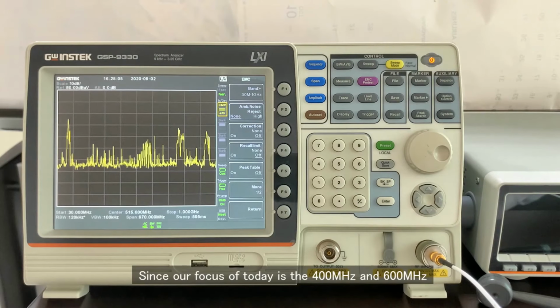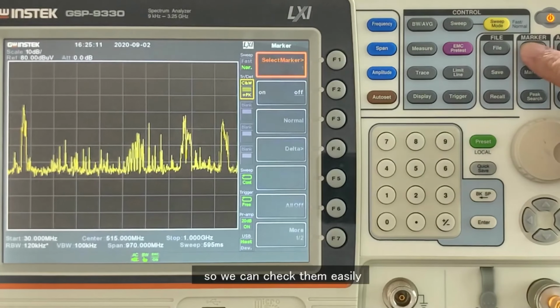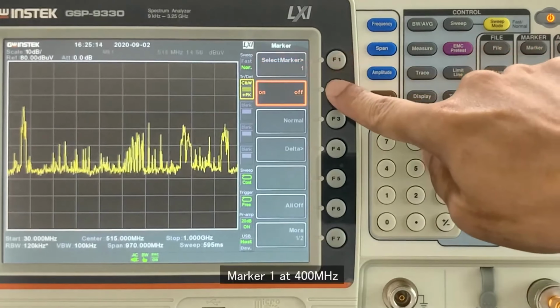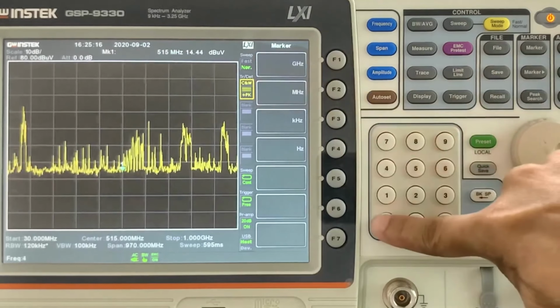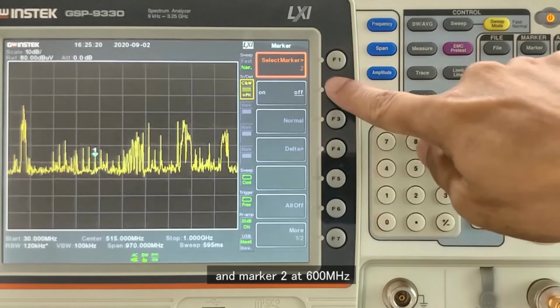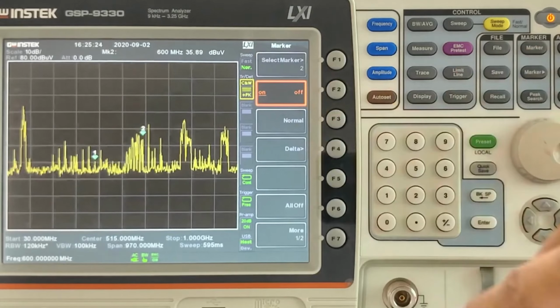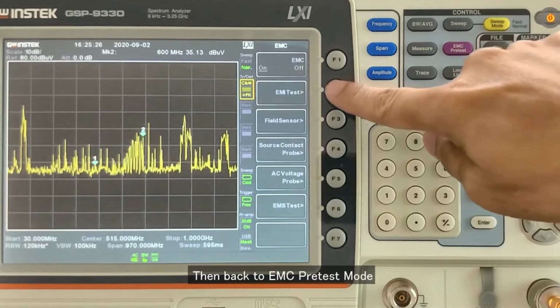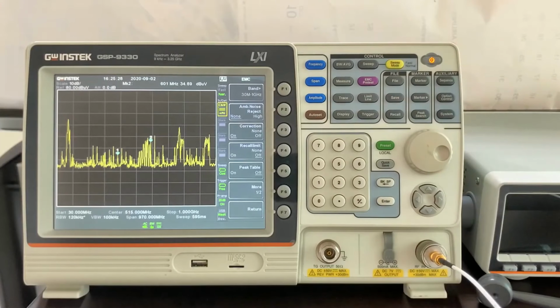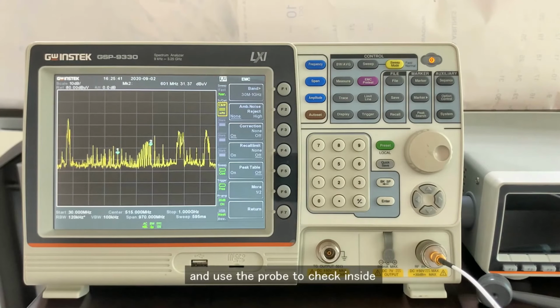Since our focus of today is the 400 MHz and the 600 MHz, let's just highlight them with the marker function so we can check them easily. Marker 1 at 400 MHz and the marker 2 at 600 MHz. Then back to EMC pretest mode. Next, we're gonna open the EUT and turn it on and use the probe to check inside.